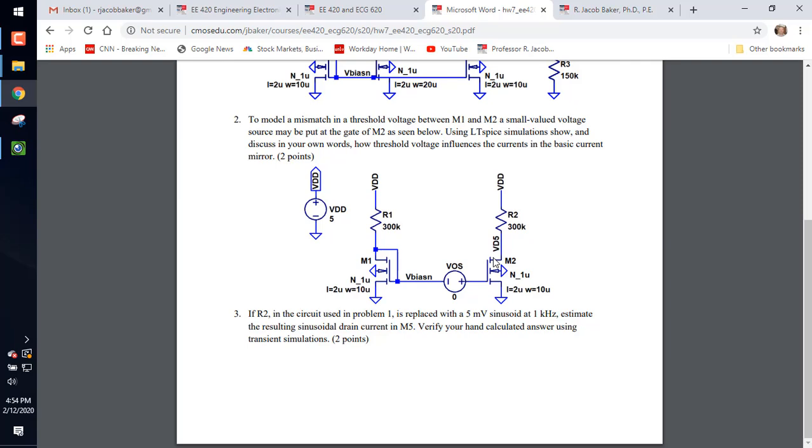So the question is now, and this is important, when you do a SPICE simulation and you put the transistors down, those transistors are exactly the same, so they match. I can't tell you how many times in industry and working with students where they come up with some analog design, and it works great in simulations where everything is perfectly matched. All right, but when you go build it, it doesn't work at all like you thought it was going to work. Okay, so there are several types of matching issues.